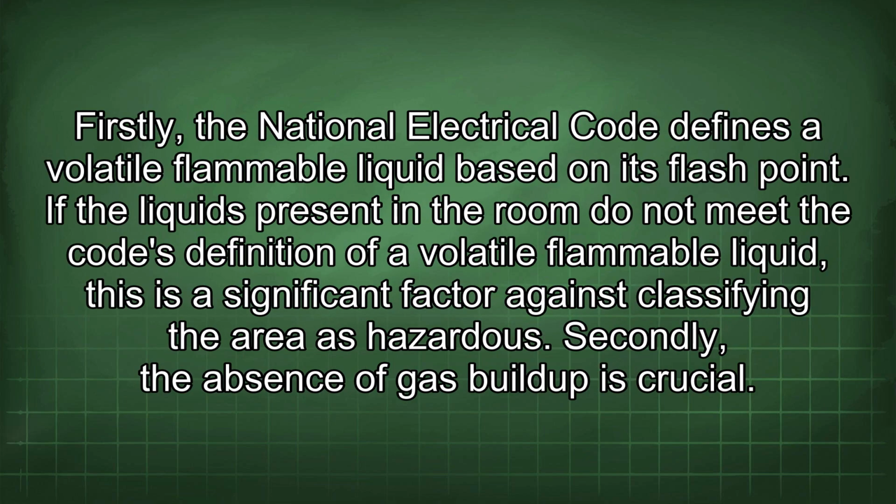Firstly, the National Electrical Code defines a volatile flammable liquid based on its flash point. If the liquids present in the room do not meet the code's definition of a volatile flammable liquid, this is a significant factor against classifying the area as hazardous.